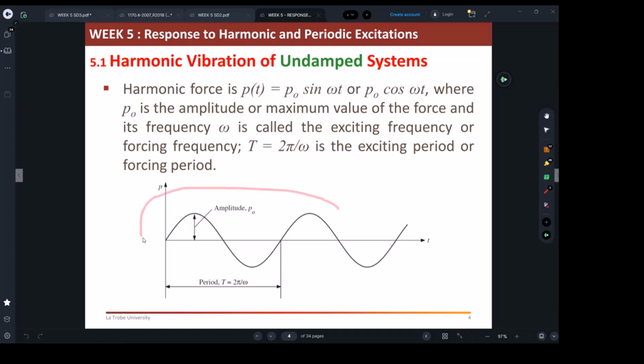Yes, this curve looks like what I showed you last week, but last week we were talking about free vibration for a structure without any damping, which is going to look the same. But here we're talking about the input frequency, the exciting frequency. All right, now start also to note the properties. For this type of excitation, or this type of loading motion, it's got a frequency and it's called a forced frequency, and it's called omega.